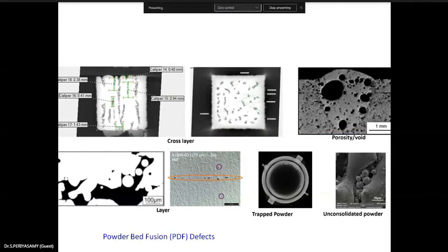So here, what is the energy, the built energy supplied, then the path, and you have the material type. So here even the crystallography structures, if you are heating, that is melting and pouring, the sintering or depositing the materials, the directionality of the grains is in opposition to the direction of the heat flux. So this is the nature of depositing, that is the grain directionality.